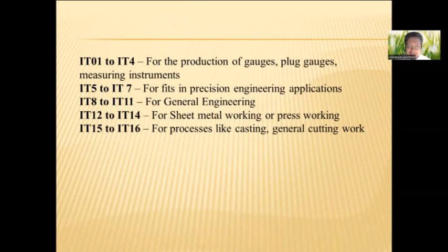From IT grade 8 to IT grade 11 for general engineering. From IT grade 12 to IT grade 14 for sheet metal working or press working. And from IT grade 15 to IT grade 16 for processes like casting, general cutting work.